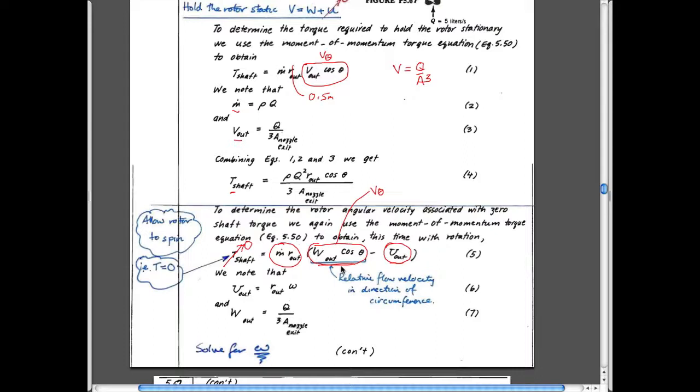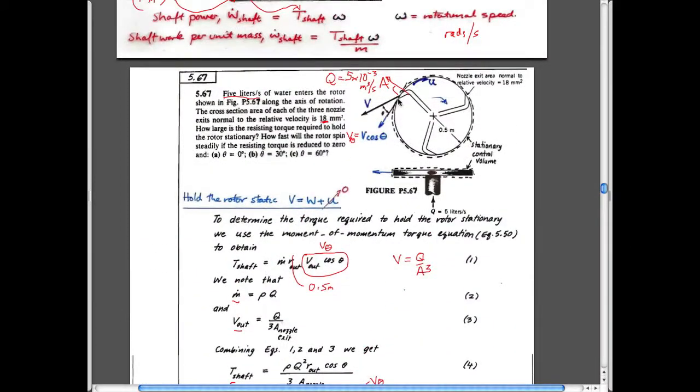The velocity of the vane, in the case we didn't do, has to be the velocity of the water that squirted at it. And in this case, the rotational velocity, or actually this is a velocity on the circumference, has to be equal to the component of the velocity which is squirted basically in this direction. So have a look at that.